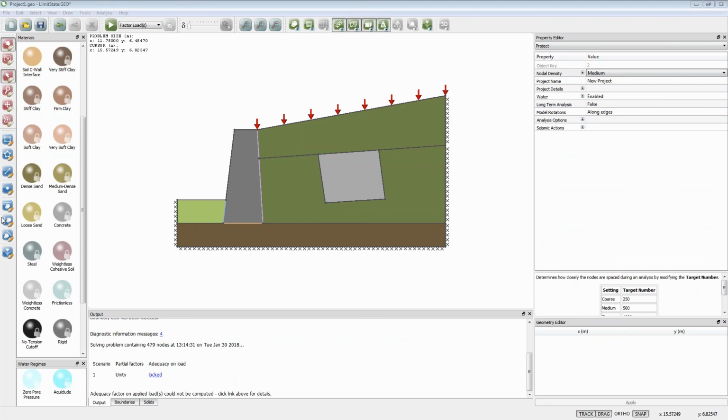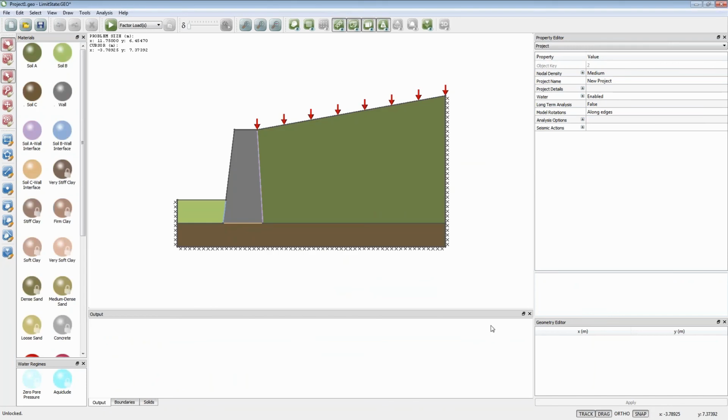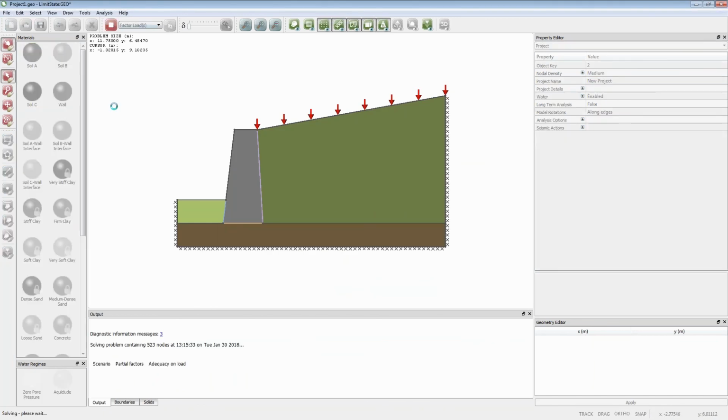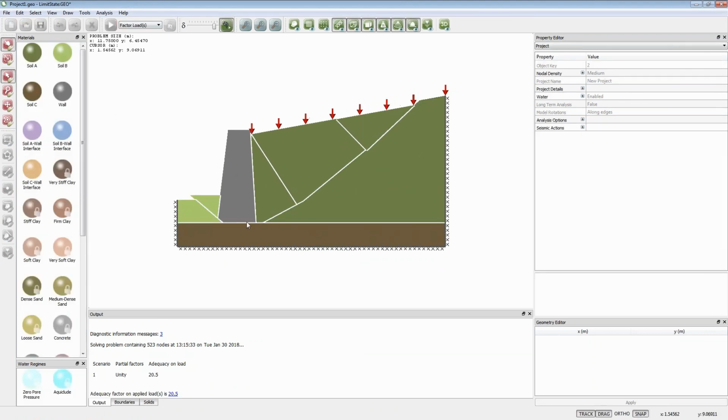All right, probably one last question. How can I calculate against retaining walls, sliding, overturning, and bearing? So if I just go back to that one. If we analyze that problem, in this particular case, the failure mode is sliding. That one is sliding along there. It's not overturning. It's not undergoing bearing failure.